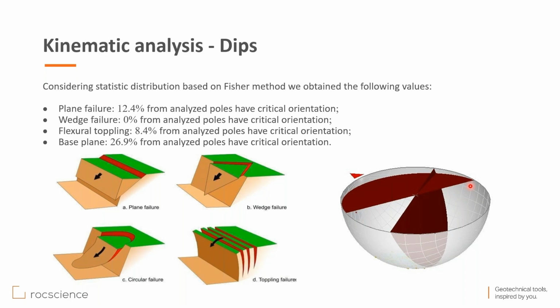Also, what I like about DEEPs is that you can have a 3D model. So here I just put two sets of discontinuities. In order to have a better understanding of the discontinuities, after you make a family of discontinuities, you can view the family in 3D. So it can be very, very useful for people who are at the beginning with this type of failures and with working in DEEPs.